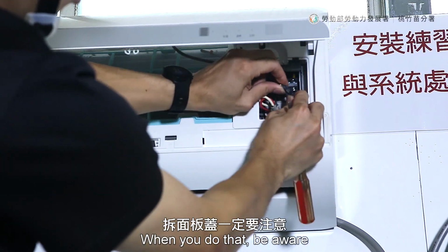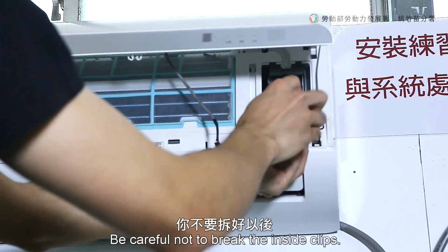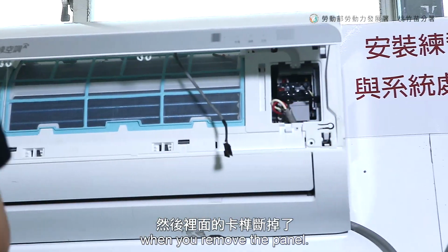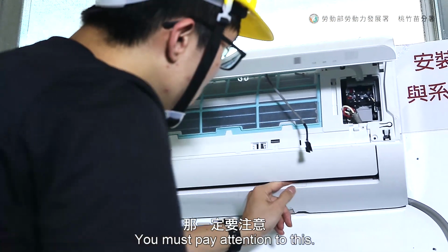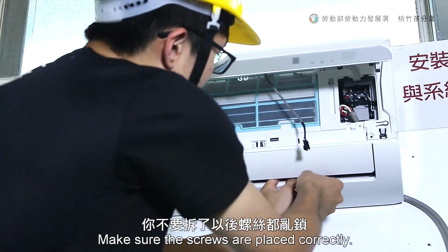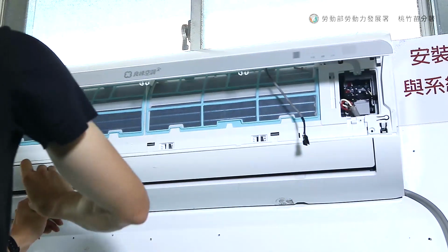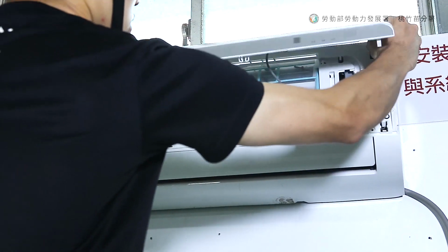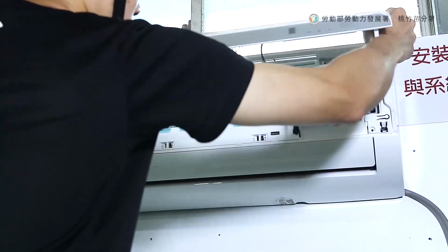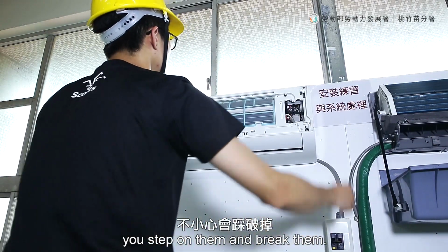When you do that, be aware there's a specific direction for removal. Be careful not to break the inside clips when you remove the panel. The screws have different lengths. You must pay attention to that. Make sure the screws are placed correctly. And don't leave the screws around. Sometimes when you leave them on the floor, you step on them and break them.